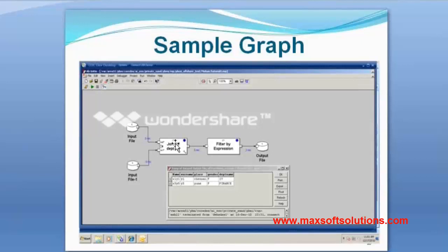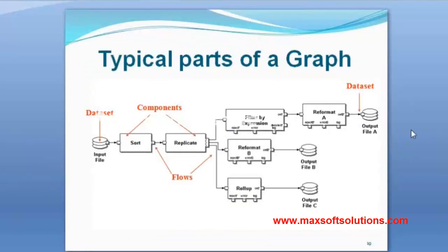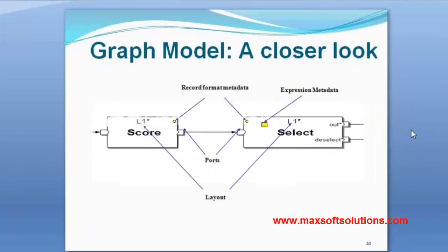You can use propagate from neighbors in the layout window, so the neighboring layout will be used. If your component is using a neighboring layout, a star will be next to it. And regarding the other marking, if the component has L in that marking, then it means your layout is determined at runtime. It cannot be determined at compile time before running your graph. So that is your information.